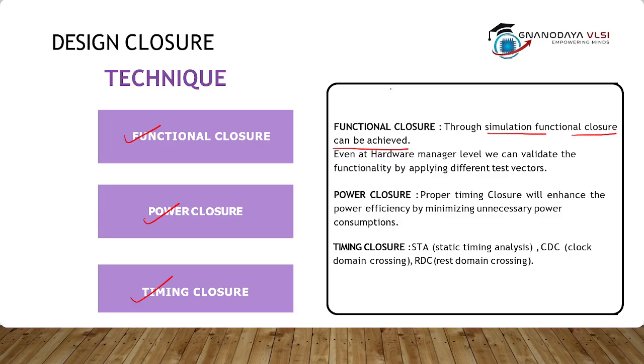Through simulation means waveforms. Suppose you are writing the code for a half adder circuit. First you need to write the design, and next you need to write the test bench. In the test bench, you give the stimulus, applying the test vectors. For a half adder, you know the sum and carry: 0 0 gives 0 0, 0 1 gives 1 0, 1 0 gives 1 0, and 1 1 gives 0 1.